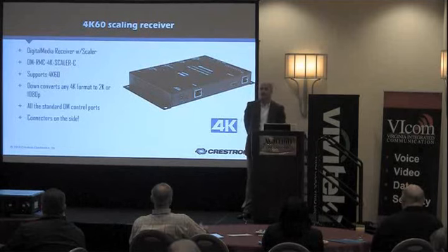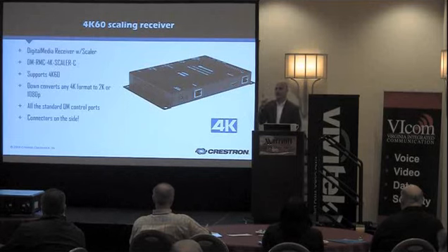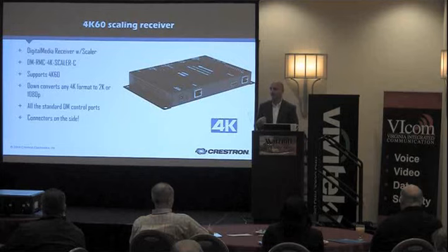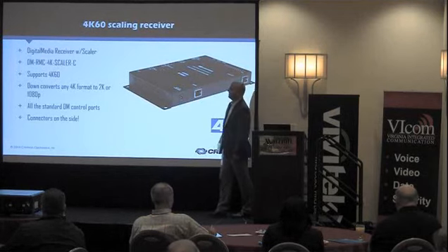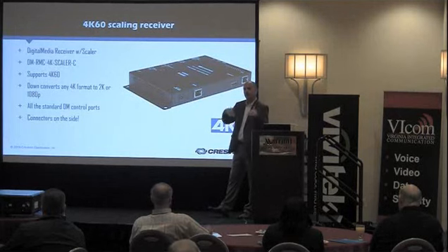But I want to take 4K content and put it on those 1080p monitors. For one of the first times in our industry, upscaling is not as important as downscaling. And that's really key. I've got to have a box sitting at the display that gives me the ability to down-res and take 4K content and push it on that 1080p monitor.